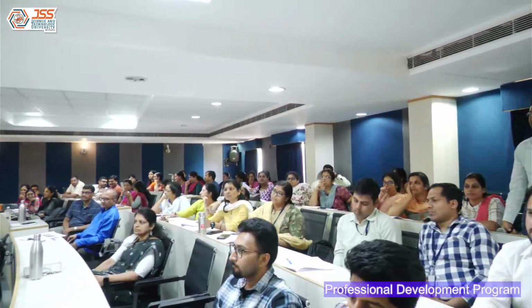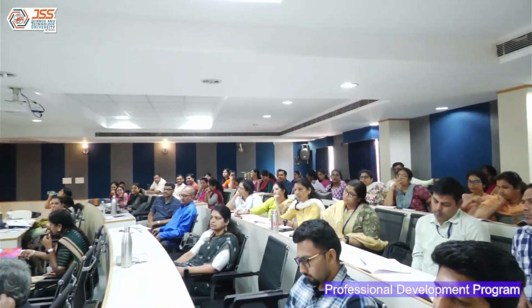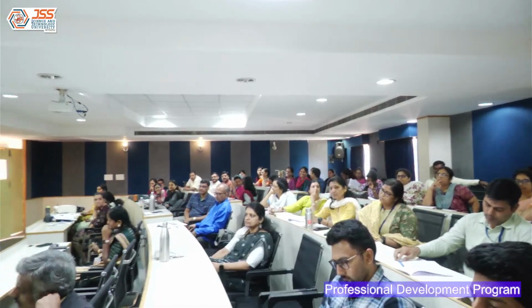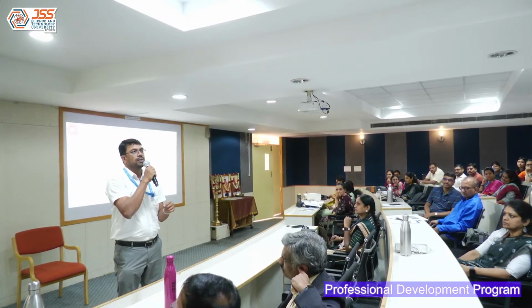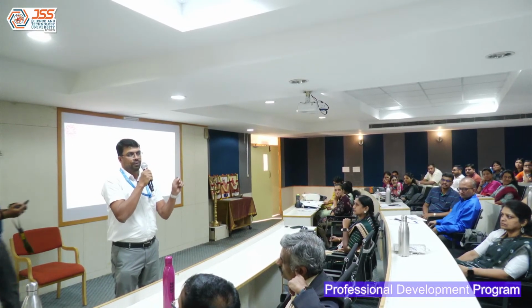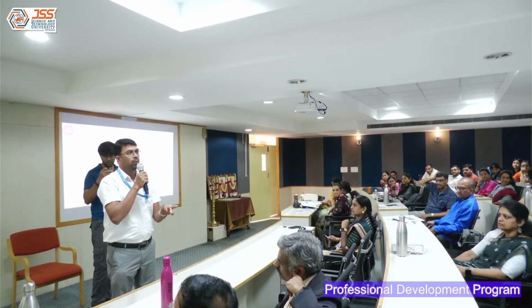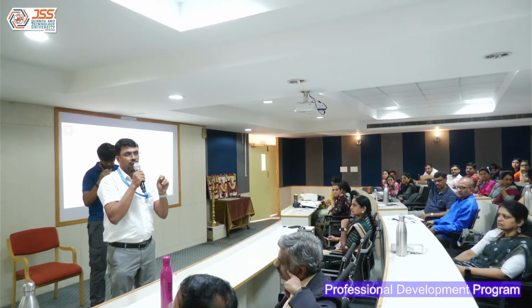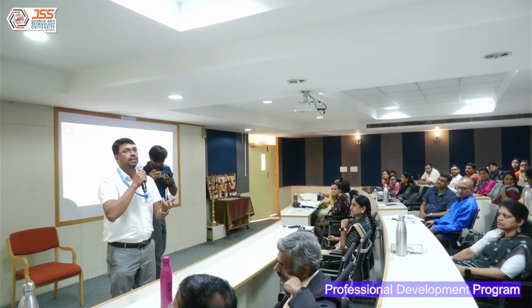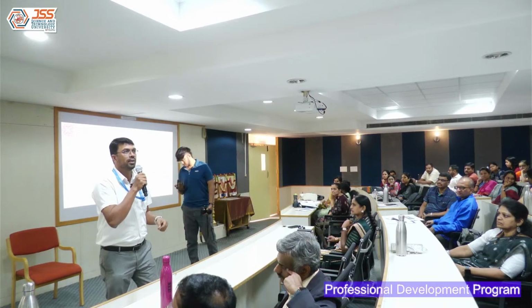Are you saying during manufacturing test or during my design? If it is part of the scan chain, definitely I'm going to test it. Only if it is non-scan, then it doesn't come under the scan chain. Is that your question, or help me understand a little better?